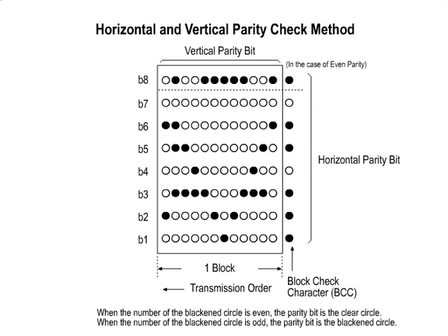C. Horizontal and vertical parity check method. Characteristics. This is a check system that uses both the vertical parity check method and the horizontal check method. Disadvantages. The combination of the vertical parity check method and the horizontal parity check method gives it better functionality than either method used alone. However, if there are even bits of the same bit position that are mangled in even bit sequences, the check cannot be done.